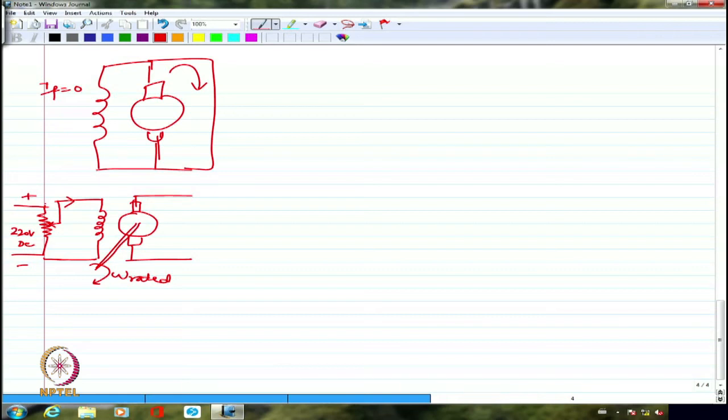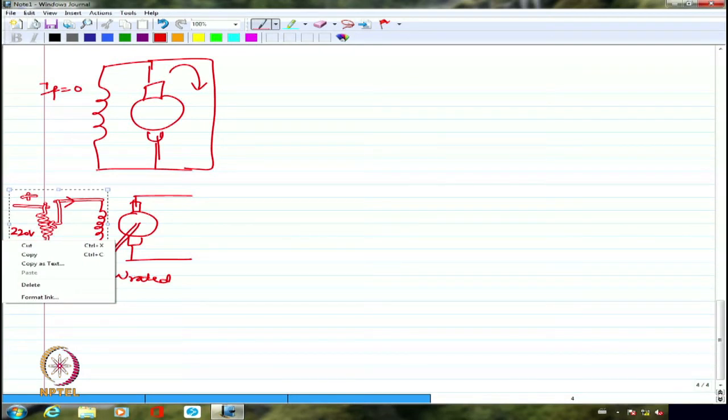So if I bring down this voltage to 0, right, with hardly any resistance included in the position, I will get literally 0 current going through the field circuit. So what is the voltage that will be generated will be the residual magnetism voltage, nothing more than that.